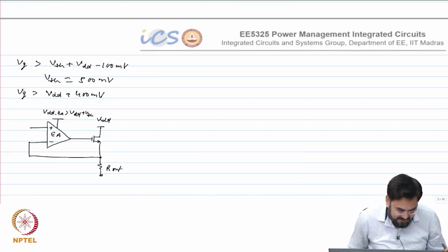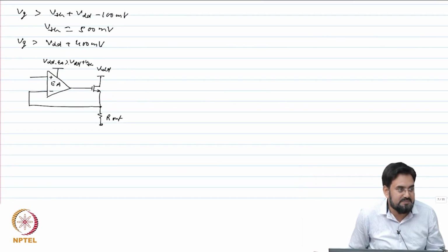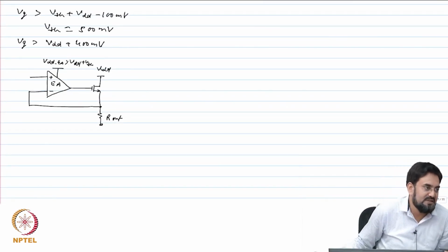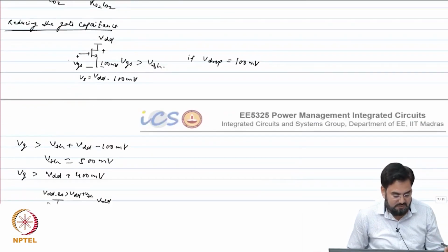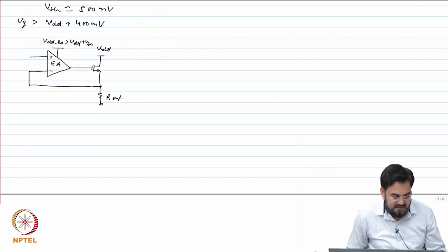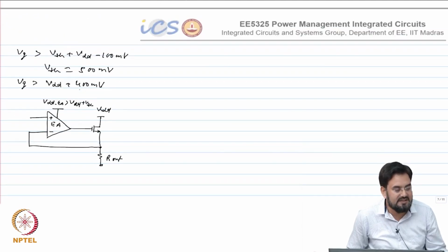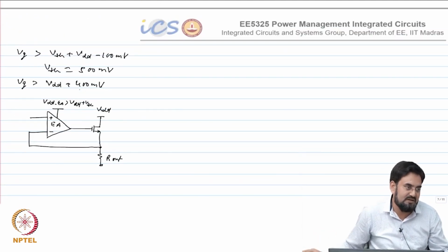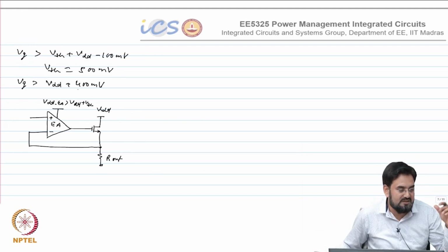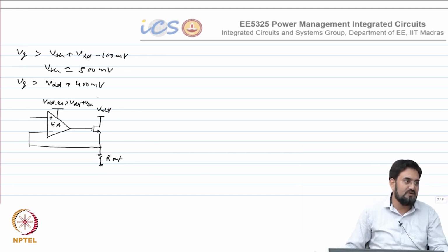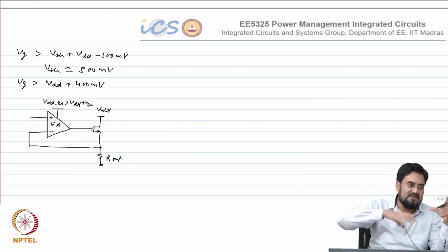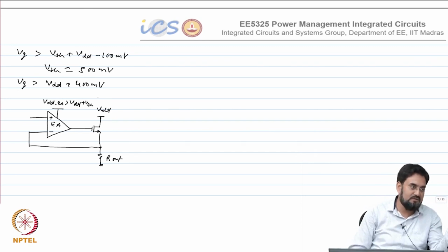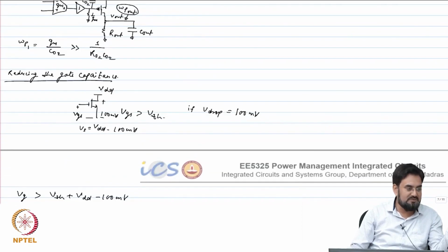And there is one more benefit on PSRR. When we talk about the PSRR, then we will see how this benefits more compared to this PMOS LDO. So both are used actually depending upon the application. So sometimes even after adding those charge pumps and everything, overall area may be less compared to the PMOS regulator, because these days the mobility factor is not just 2, it is more than 3 or so, 3 to 4 times. So you will get a huge area advantage with this. So even if, let us say, after adding charge pump the two have the same area, the performance of this may be better compared to your PMOS LDO in terms of PSRR and all those.